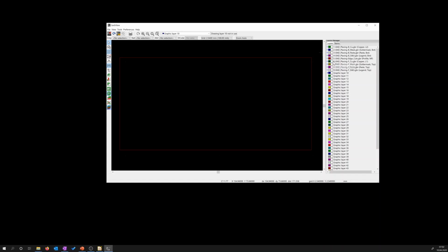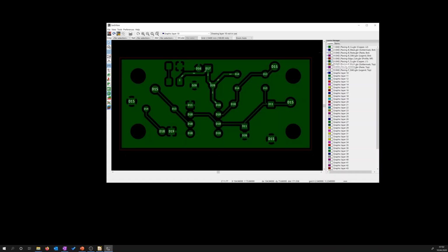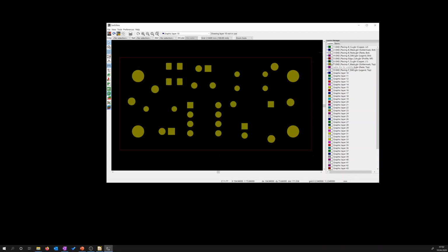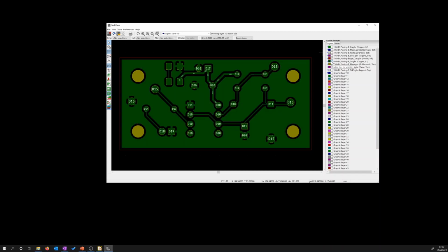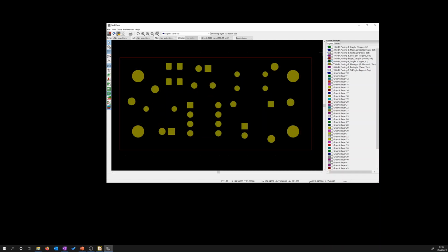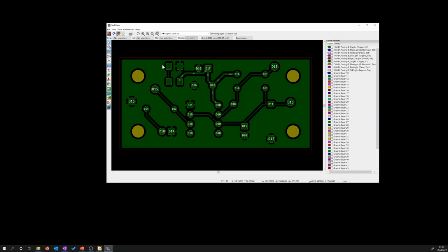First we check again the copper. We select the copper fields, we see our routing, this looks fine. Then we check our solder stop mask for the top side, it's the same game. We check if the windows of the solder mask are at the places of the holes and the pads for our SMD. So let's take a little bit care about this because it's new for us, SMD devices. Looks also fine. And at this time we can also check where solder paste is dispensed.